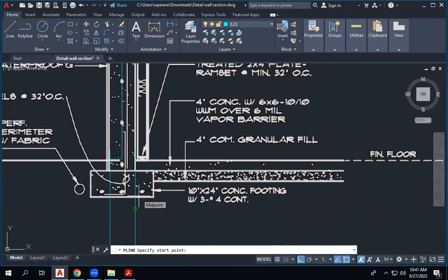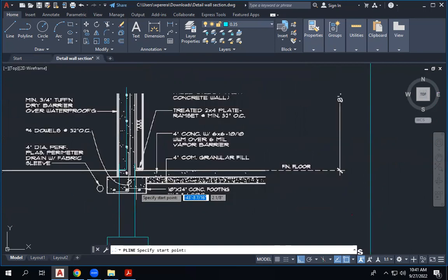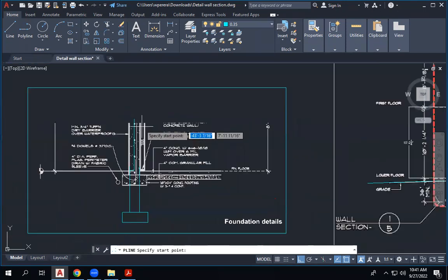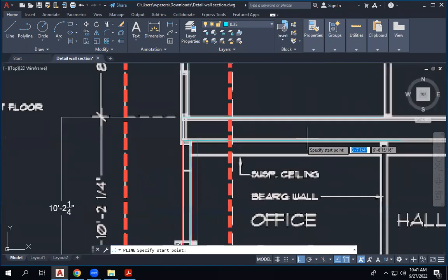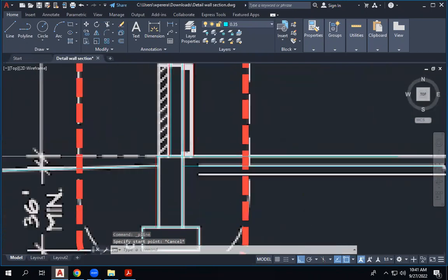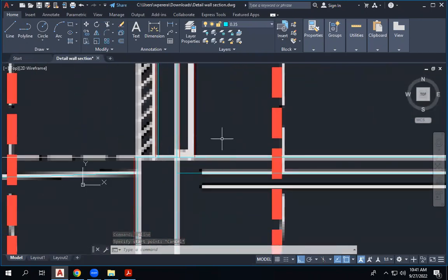So we took a section. In that section, only the bottom section is cutting, and also the top one is not here because the detail is stopped at this point. We will have another section at this level, the same as we have at the bottom because it's a frame. So what we do is we will draw two timber studs here, bottom and top.